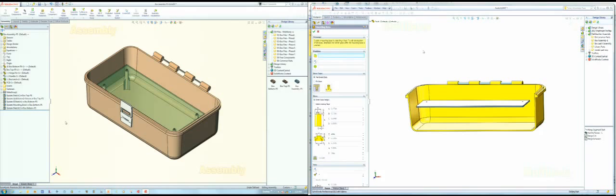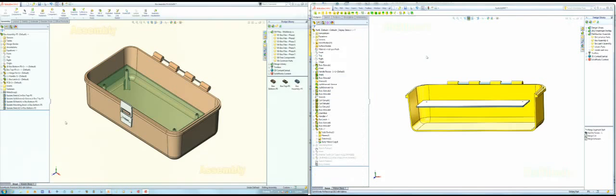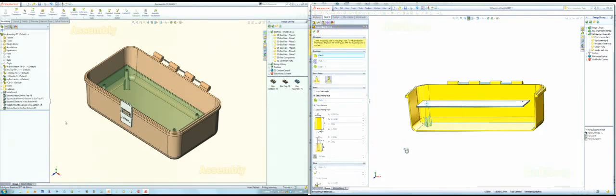Okay. New for 2013, they've added some types of mounting bosses. But it kind of acts funny. Right now, if we're adding one, you can see there's a bunch of choices here, right? But if you're going back and editing one, like this one, so I'm going to unsuppress this mounting boss I did previously, and if I edit that, you can see some of your choices are gone.